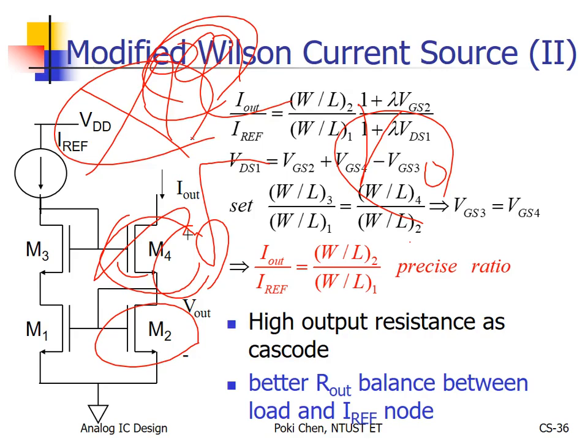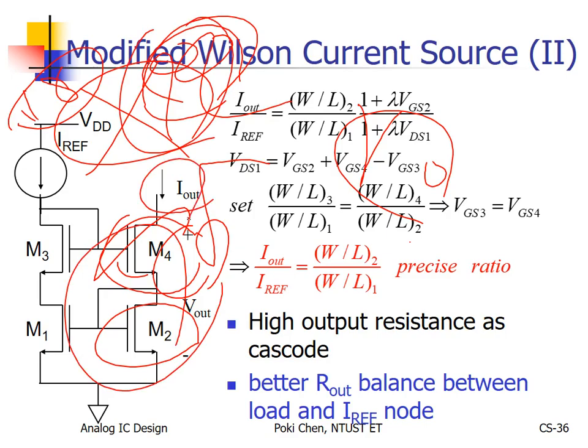So what I mean is usually you need to apply cascoding to both sides, to NMOS and to PMOS, right? So what is the consequence? Even with 0.18 micron, such a very old and mature process, it means what? Cascoding here, cascoding there, then the operation range will be really, really small. Only a few hundreds of millivolts. 200, 300, no more. Okay? Oh, that is really tight.